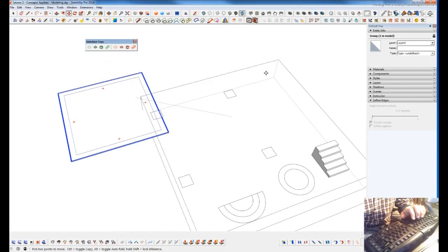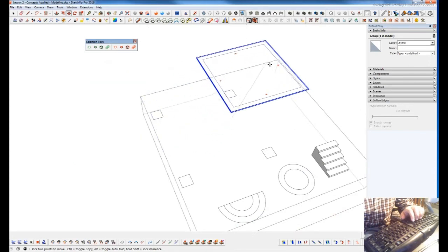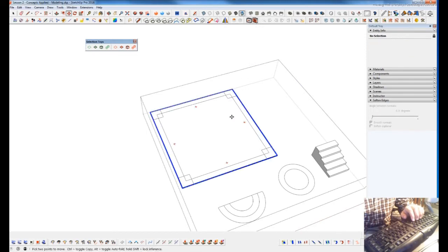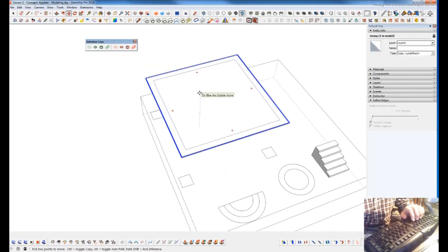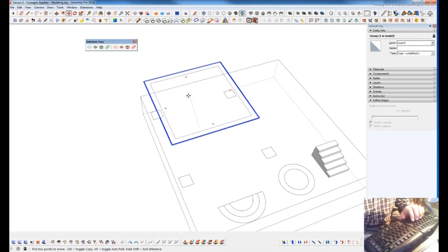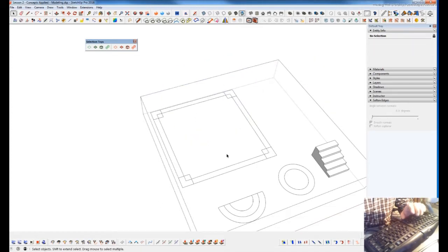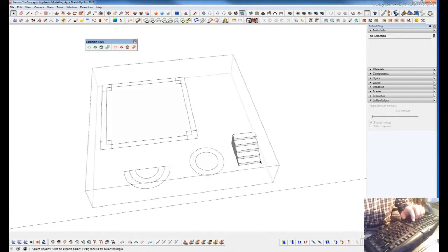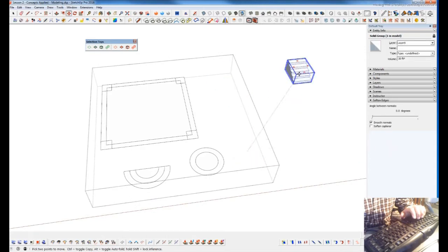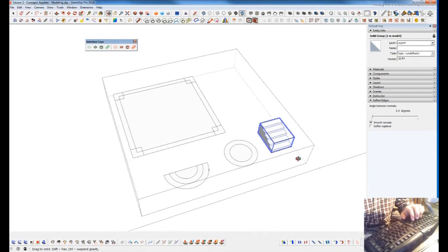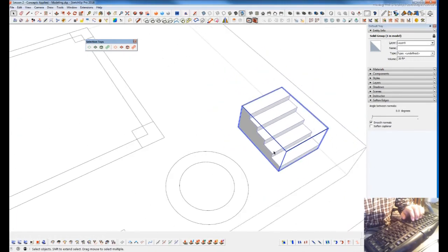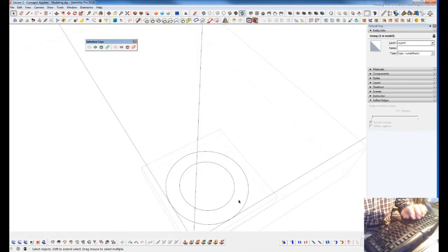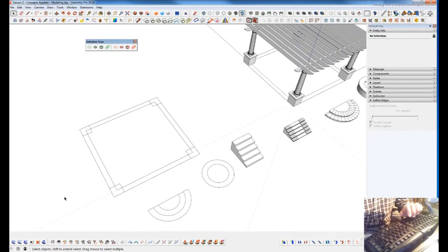So if you're in a move tool or something and you want to let it go in mid-operation, instead of, darn it, click and then undo, if you grab it and you're moving, and again, I just tapped it, my finger's not on the mouse button anymore, I can just hit the space bar and it gets out of that tool and drops whatever operation it was in the middle of. So the space bar is something you want to get really comfortable with, and you say, I messed up, I don't want to grab that. You just hit the space bar and it drops the tool and puts back whatever you were working on. So obviously for selecting and things, you're going to be hitting the space bar all the time.